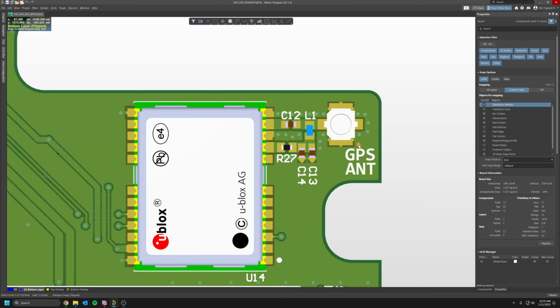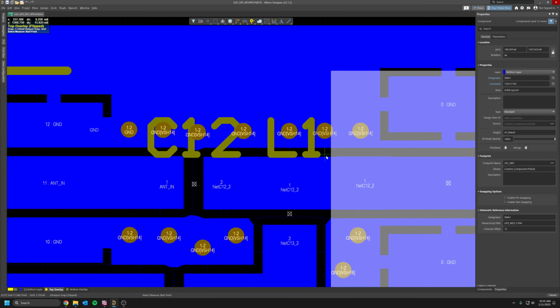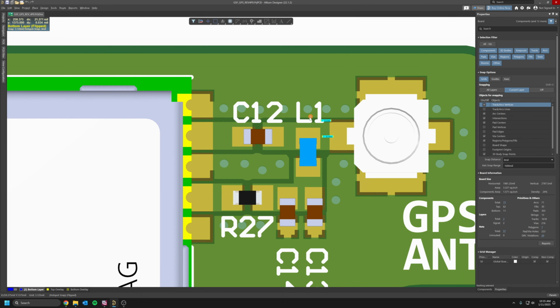Also, this is only a 2-layer PCB on FR4. For the traces, for instance, I'm using 39 mils in width, with 6 mils of clearance, with a coplanar waveguide with vias around it. So that's what you see here.